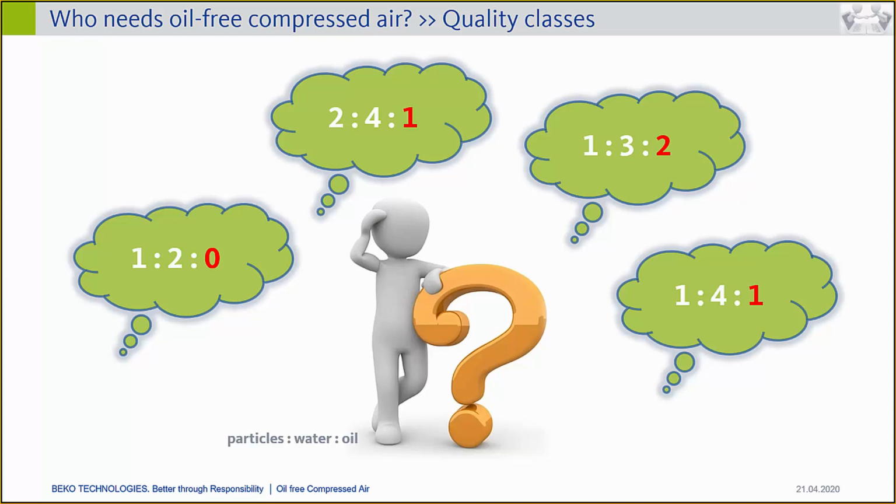You may all know that a compressed air station or system is a quite flexible and dynamic operating system, and we often run the risk of peak loads, of peak values in between. Once you have a quite low setting of alarm values, these peak values may trigger an alarm, and that may shut off the valves, so finally there is no airflow for the application.